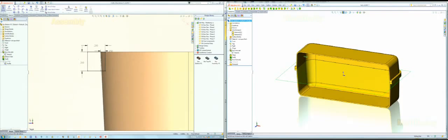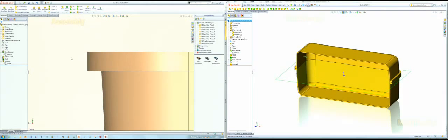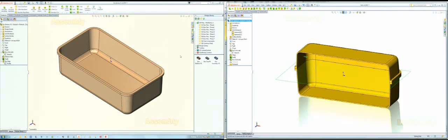and it's just a little box. If you're going to sweep around the edge of something, it's always a good idea to make sure you have contact all the way around, so that's why there's a construction line in here, and that just gives us the boss. Now to that, I'm going to go into the assembly.